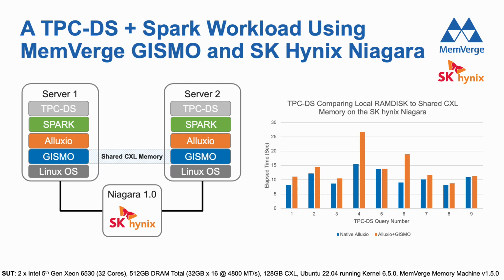Now, when comparing the first 9 results from the 100 we ran in the TPC-DS benchmark suite, comparing CXL memory from Niagara to the Ethernet and DRAM solution, we do see Niagara is slightly slower, but really not that much slower. And given that Niagara is using PCIe Gen 3 FPGAs, the results are rather encouraging, and we definitely expect the performance to improve as the hardware evolves.